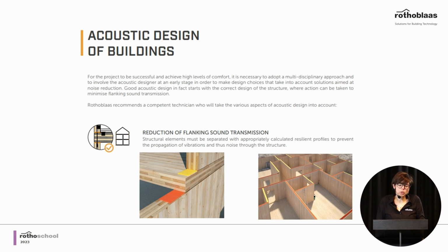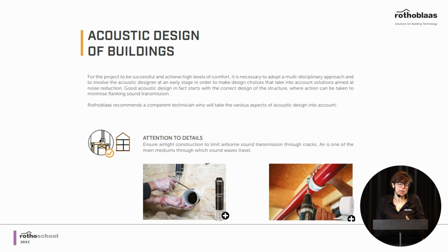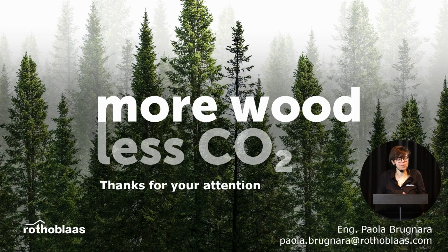Pay attention to the reduction of flanking transmission. We have seen that this is an indirect phenomenon that causes the propagation of vibration to the structure and can worsen a lot the final acoustic performance of our separating elements. And at the end, pay a lot of attention to details. We have seen that air-tightness and decoupling the components is very important to guarantee the acoustic performance of the whole solution. This was everything from my side.